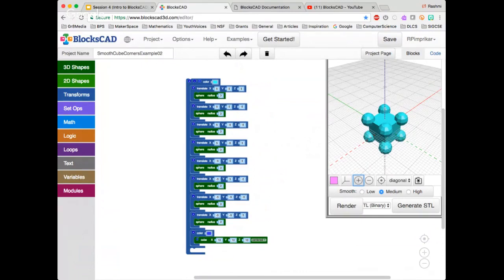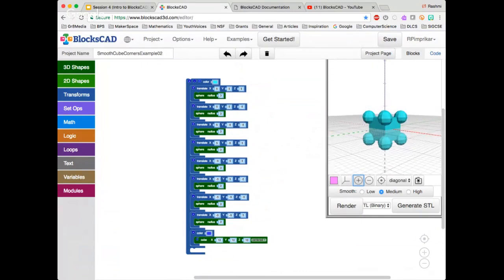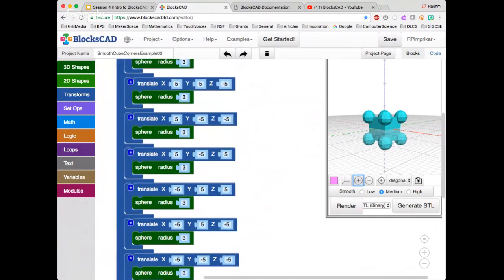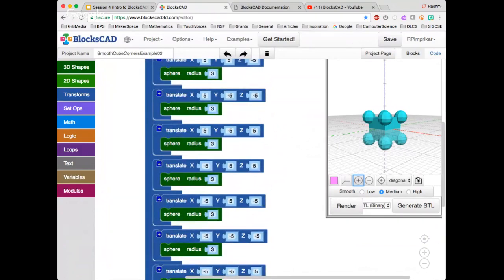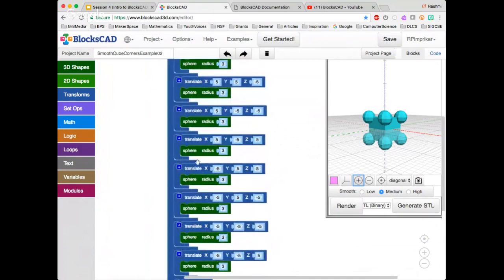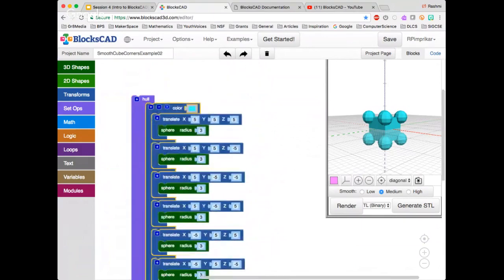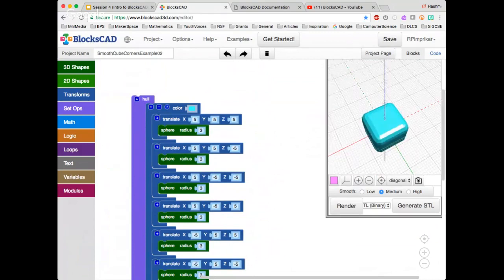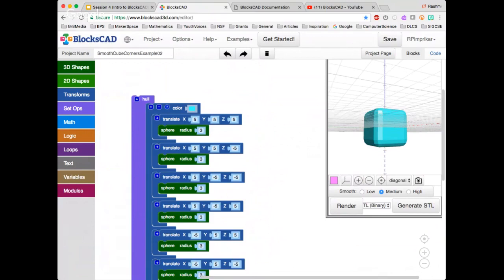So you can plan it and design it accordingly. Obviously, we have used translate to place the spheres at the corners of the cube, and then I'm going to use the wonderful setup, which is the hull, and place this inside the hull. I'm going to render it, and that's going to give you the cube that we showed. Of course, you'll have to start putting either 1, 2, 3, 4 or whatever operation, plus or minus, that you would want on the sides of this die.